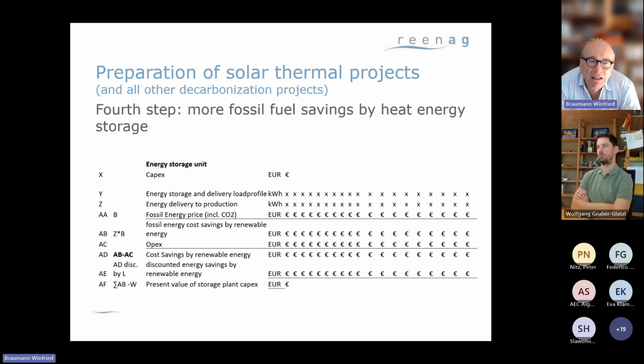In modeling, a heat accumulator is an energy cell that has both a load profile and an energy generation profile at different times. The coverage of the load profile of the storage has to be derived from the generation of energy surplus by the solar thermal power plant, and the heat release profile has to be matched with the load profile of the production plant for the energy demand, which is not covered by the solar power plant.